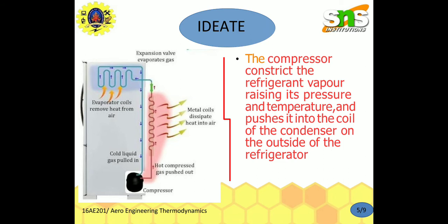Components corresponding to the condenser and evaporator in a vapor compression cycle are the hot and cold gas-to-gas heat exchangers. For given extreme temperatures, a gas cycle may be less efficient than a vapor compression cycle because the gas cycle works on the reverse Brayton cycle instead of the reverse Rankine cycle. As such, the working fluid never receives or rejects heat at a constant temperature.